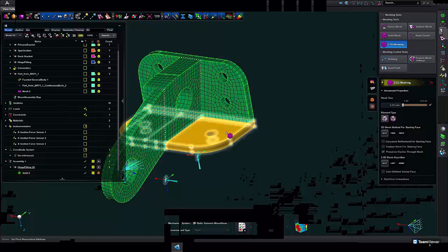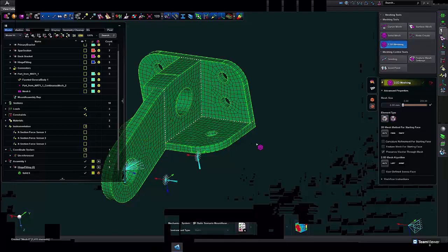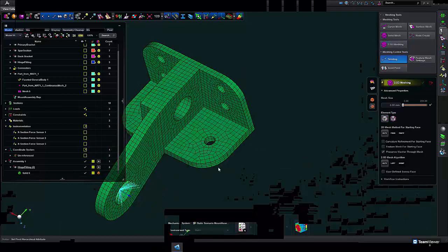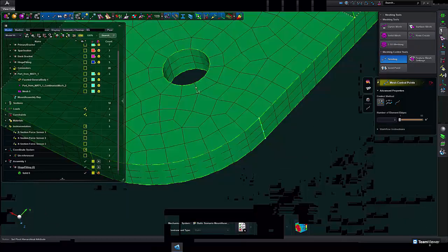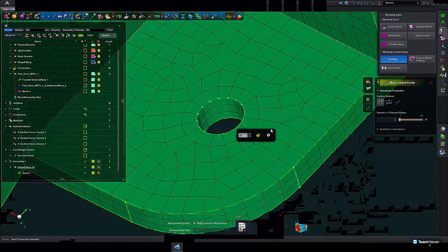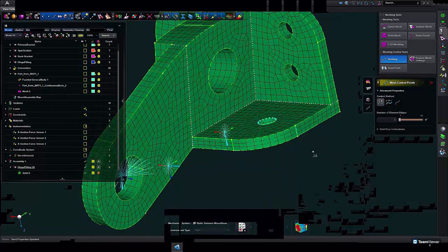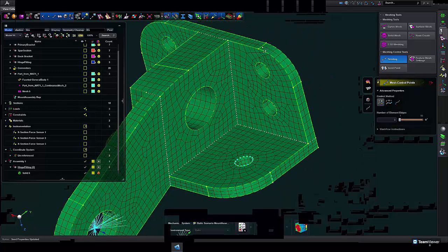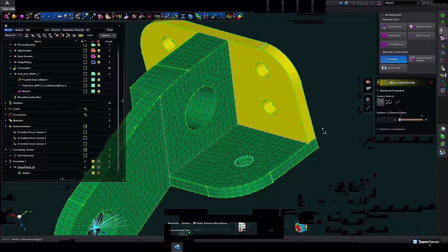So if I now only mesh this body, I can mesh it again. Right, so that diagnostic tool helps quite a bit, specifically when you can't see what the reason is for the fact that it's not hex meshable in the first instance. But that will only occur when there's an incompatibility problem, like in this case.